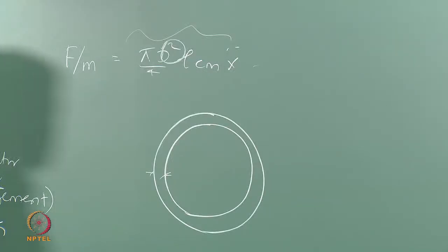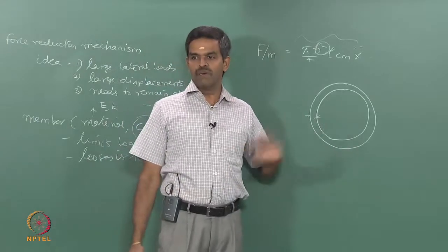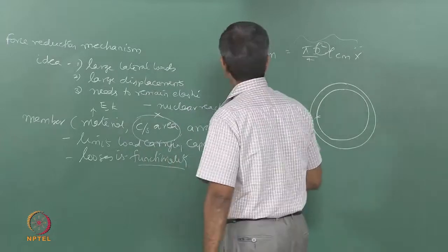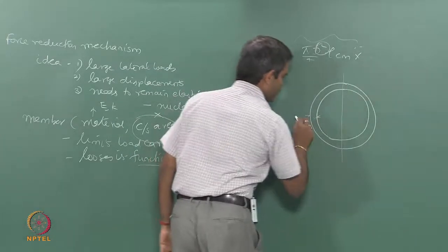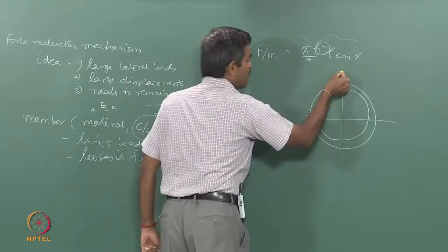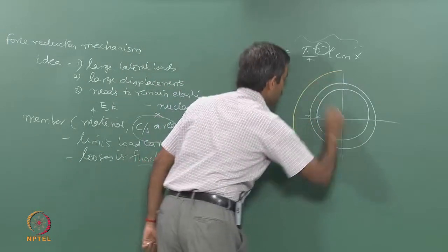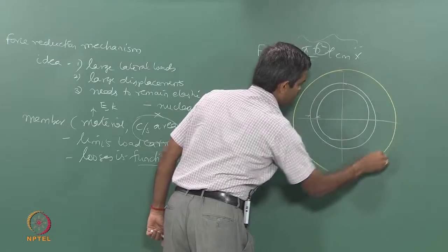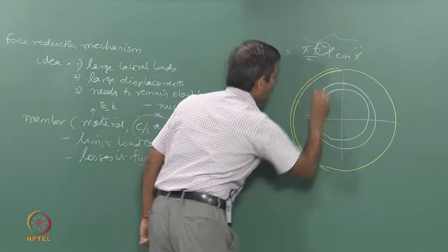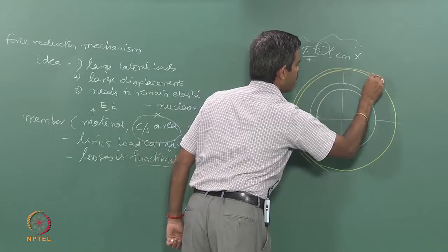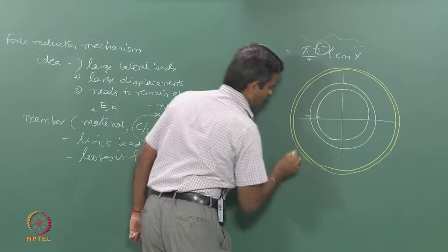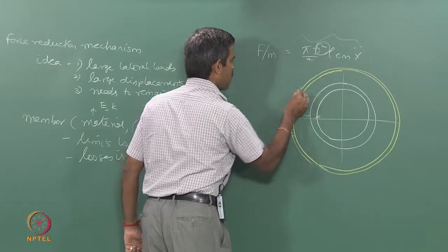What is the consequence of D by T violation in terms of stability of the member? We know that. Okay. Now, I have a large member, a large diameter. So, what I do in this case is, I try to put an external cover on this member, which is also of course annular, which is also a tube, and this will have a lot of perforations all along the periphery.